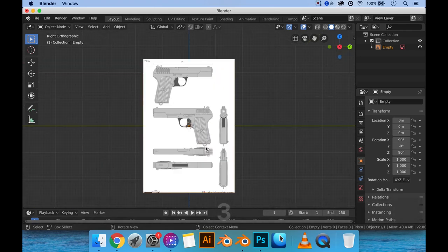We are just going to go ahead and rotate this guy. I am going to actually duplicate it, Shift D, click, and reset this back to 0. Go into front view. As you can see, it's a duplicate of the image right there. I'm going to have to slightly shift this so that the front side of the barrel is sitting over here, and I am going to turn on snap mode.